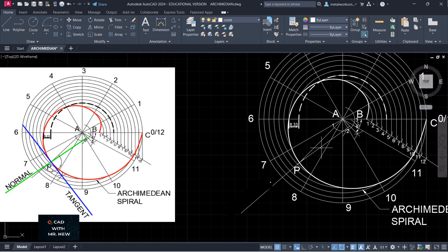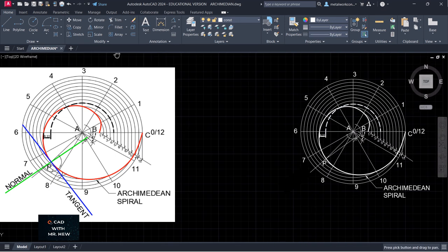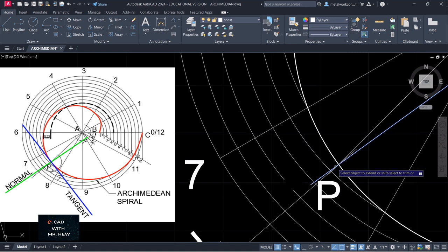Now, that we drew a while ago, okay? So we're actually going to extend this line. So we need to draw, let us center it so that you can see it. We need to draw a random line out here, like this. Enter. And we need to type extend, to use the extend command to extend this line. So there, zoom it up, there.